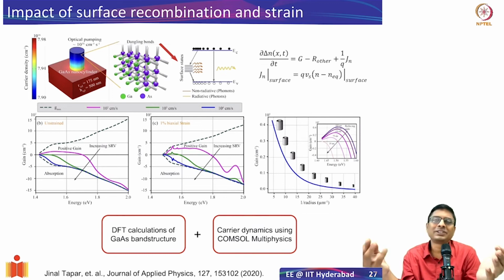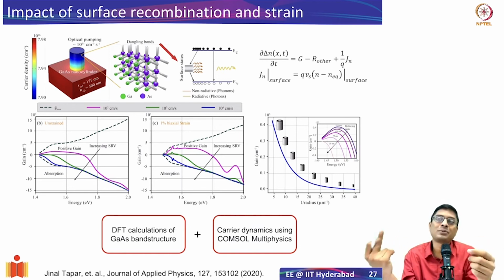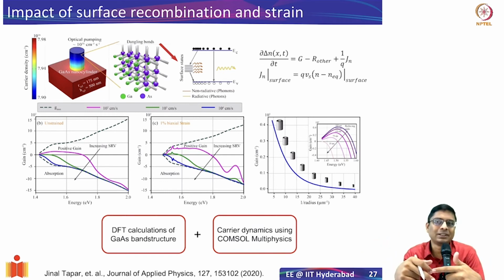We create basically the surface recombination current. I could define it in a way that it's the charge times the number of carriers times the surface recombination velocity. So if you have a large surface recombination velocity, that means a lot of carriers are recombining. It's a metric essentially, and it turns out that the speed with which the carriers move towards the surface is an important parameter. There's a lot of interesting semiconductor physics there. If you're working on that, we can talk more.